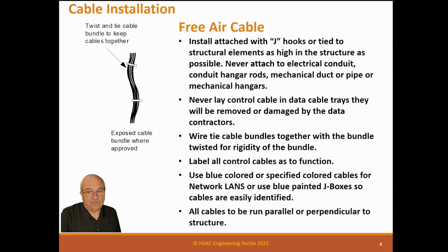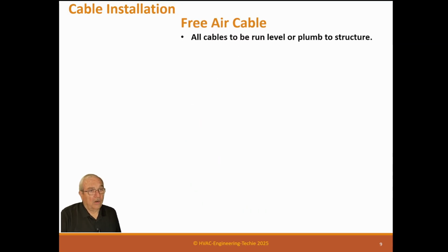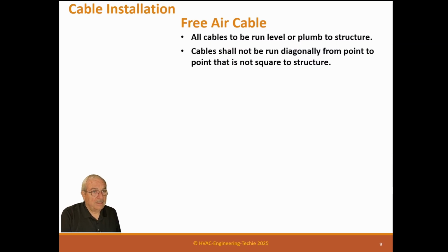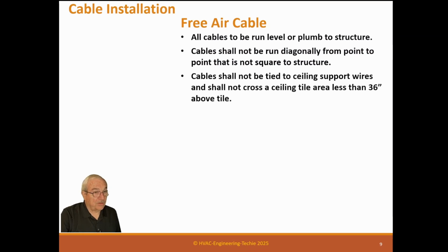All cables to be run parallel or perpendicular to structure. No point-to-point runs of wire. Remember, we're trying to keep these out of harm's way, and if you run point-to-point, your wire is going to be damaged, so don't do that. All cables be run level or plumb to structure, kind of what I just said. Cable shall not be run diagonally from point to point that is not square to structure.